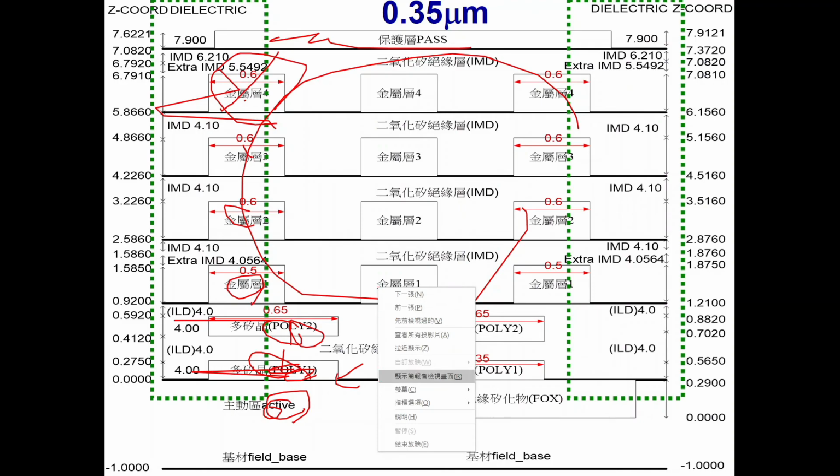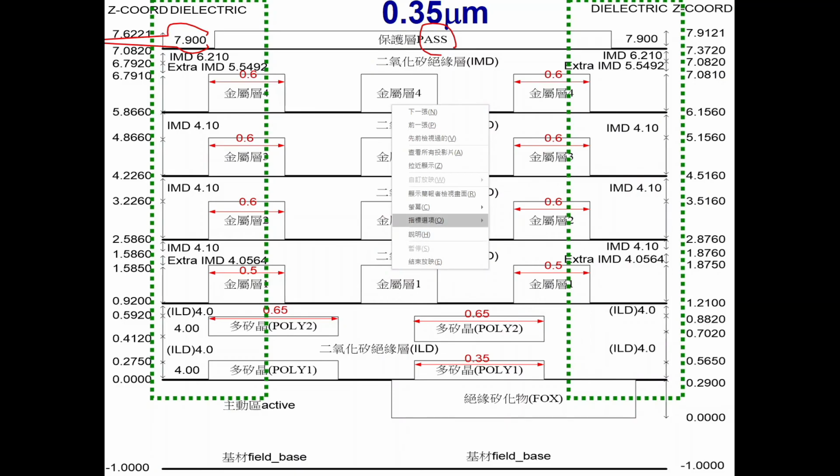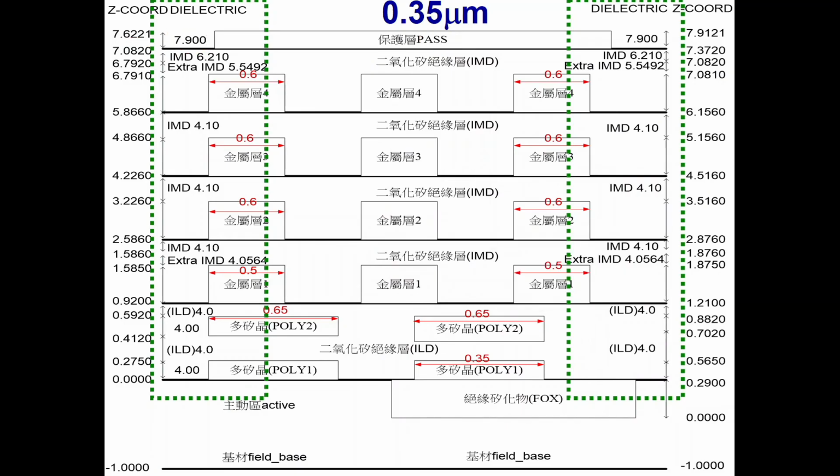So we need to insulate the whole chip from the air. But you need to have some kind of opening, because your pads, I/O pads, and probing pads cannot be insulated by the glass. No. They need to be connected to the outside world. So we need to have such an opening here. We call it the passivation window.